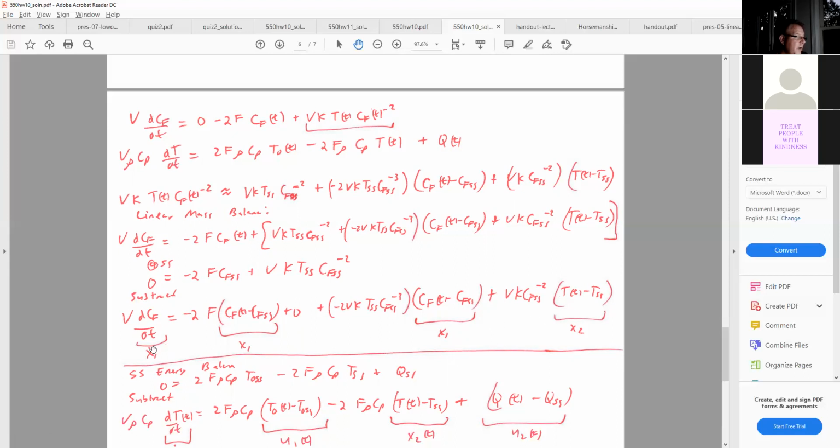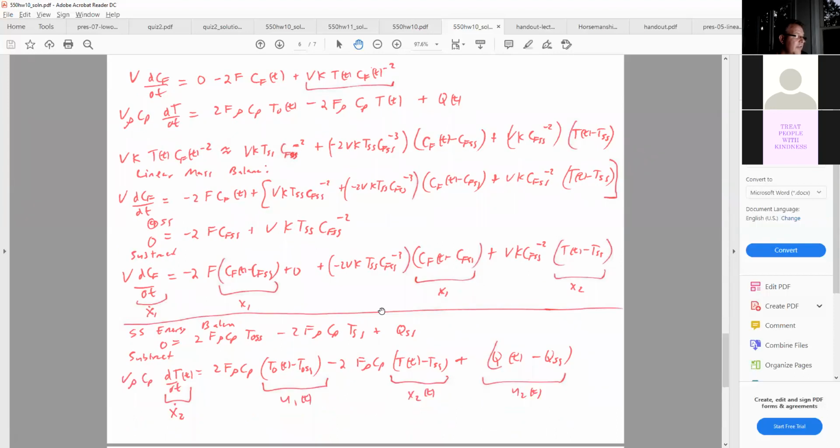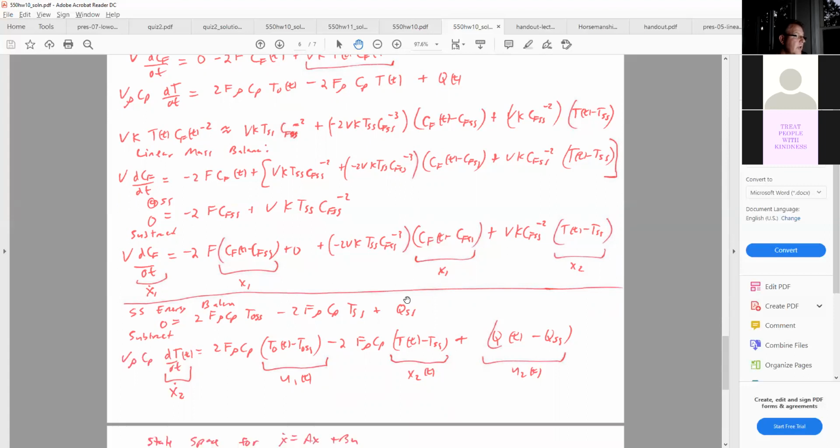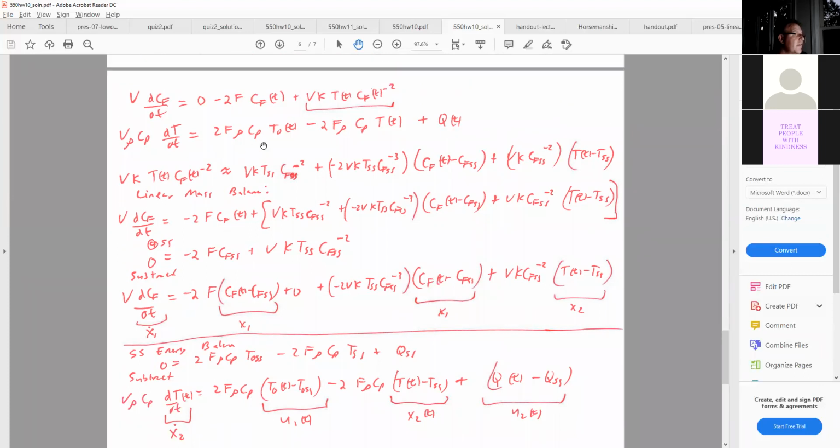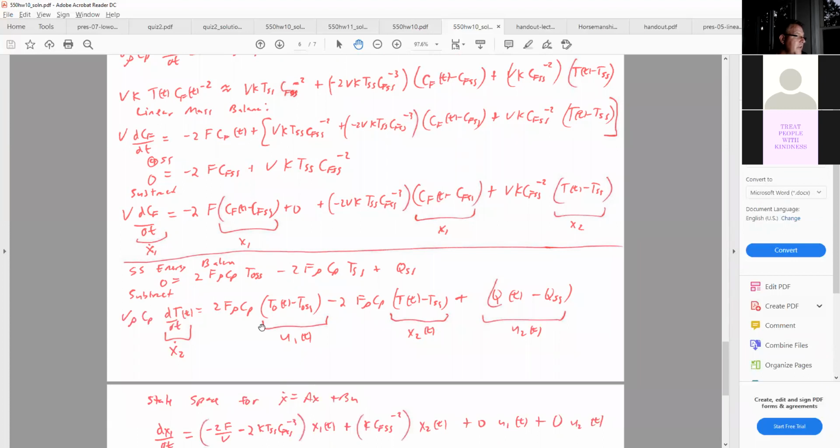So when we change all the variables, it's just a bunch of x's. U doesn't have any effect on the concentration. Y's are measurements, U's are inputs. On the energy balance side, the energy balance is all linear. You have the feed temperature and the steam heat and the flow out. So the feed temperature is an input. The steam deviation is an input.